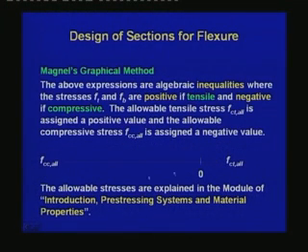Whereas, when a negative stress, its numerical value has to be less than the numerical value of FCC allowable, then if we write the algebraic equation along that axis, we have to write that the stress is greater than FCC allowable, since as we move from left to right, the values increase in an algebraic sense.